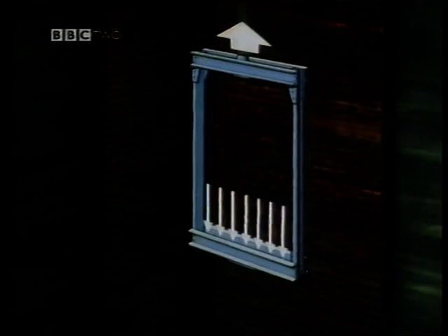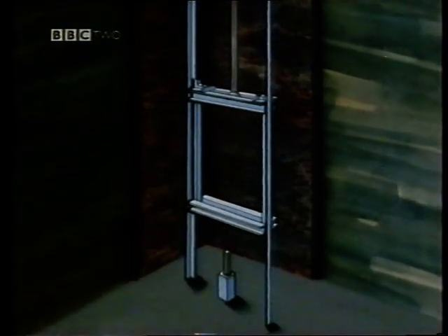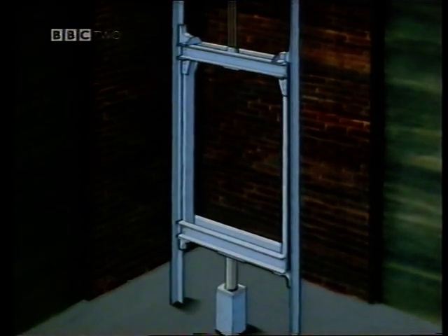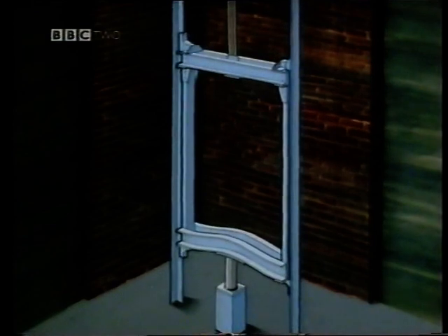But as with the drum system, there are certain safety features, and these in turn are going to affect the forces in the car frame. The car itself runs on guide rails. The guide shoes on the car keep the path of the car in line. Should the car approach too close to the base of the shaft, a buffer will absorb the kinetic energy of the car, and under these circumstances, the base beam undergoes bending upwards.